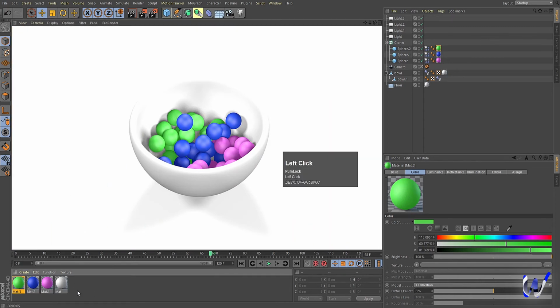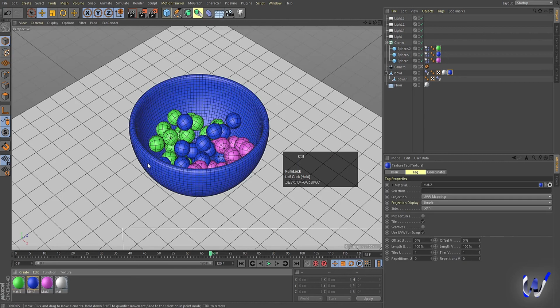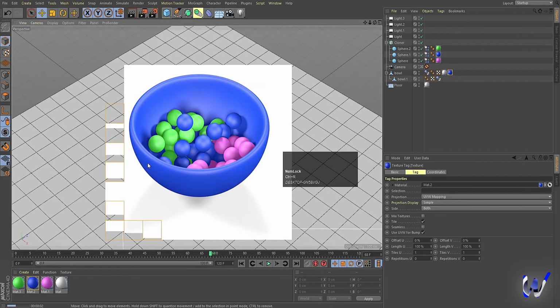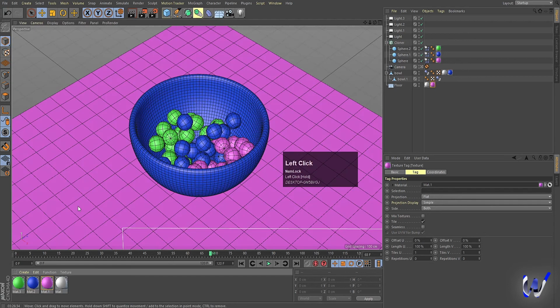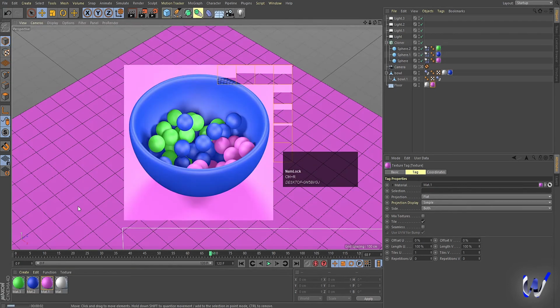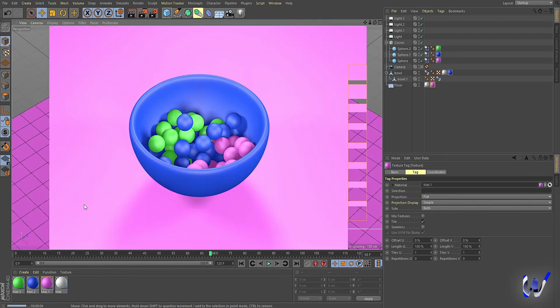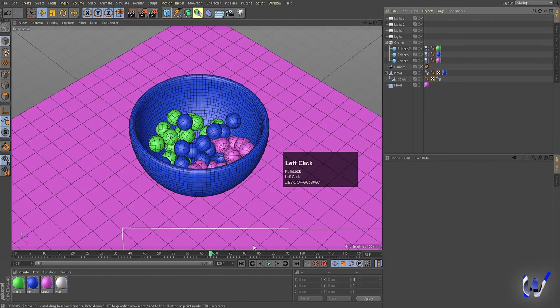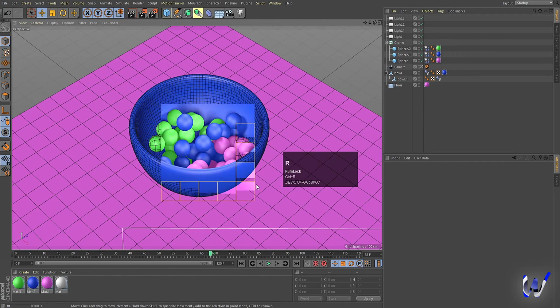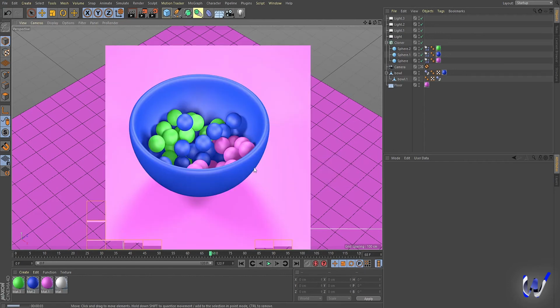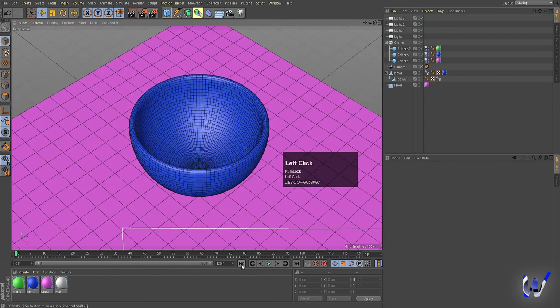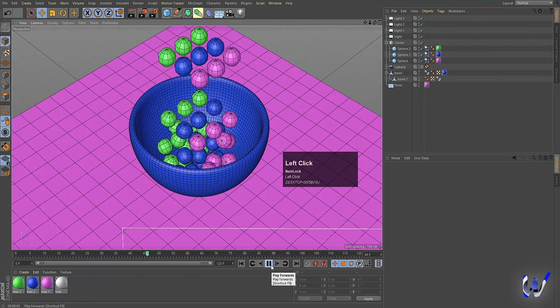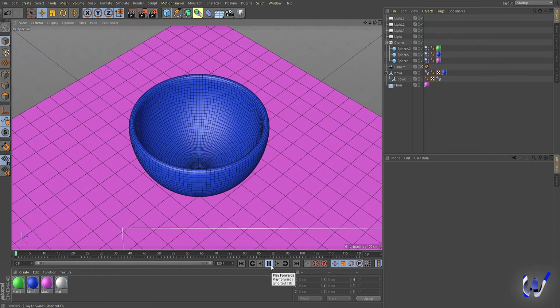Or if you want, then you can apply any of these colors to this one. Yep, this one also looks good, and you can apply this color to this. Yep, this also looks good. So let's delete these white things, we don't need that. And as I said, we will get this kind of stuff, and now your animation is ready to render. So as you can see, with the help of simple things, we can create this kind of looping animation with the help of C4D Dynamics.